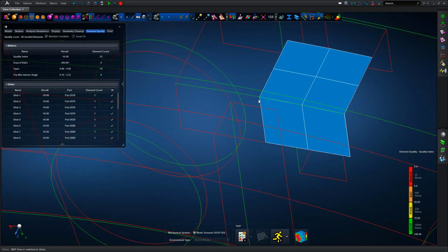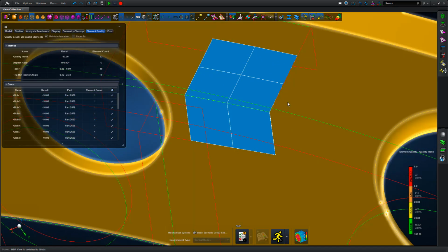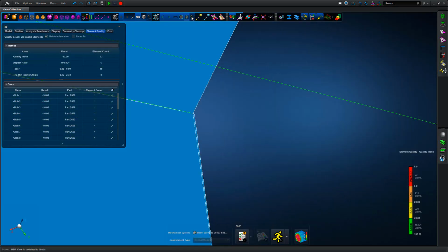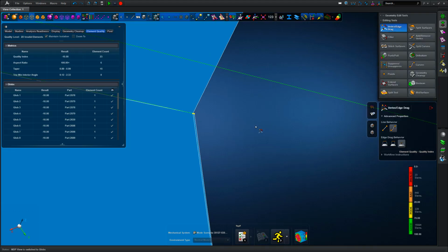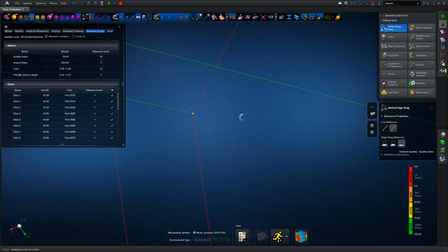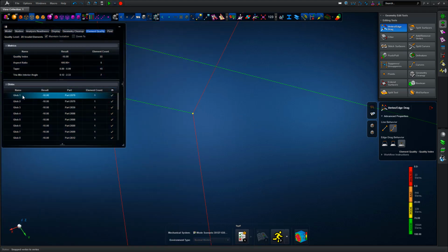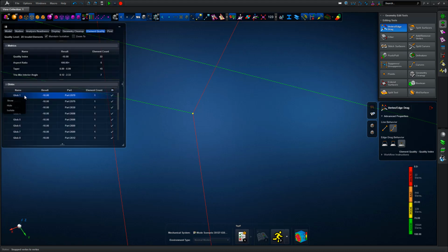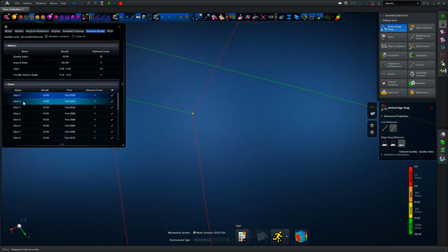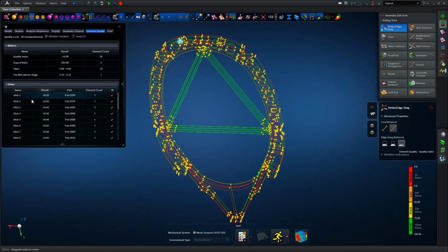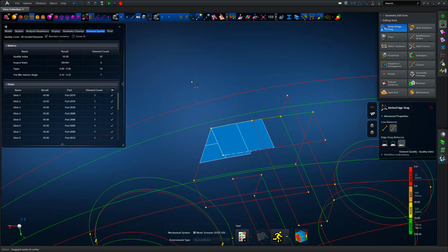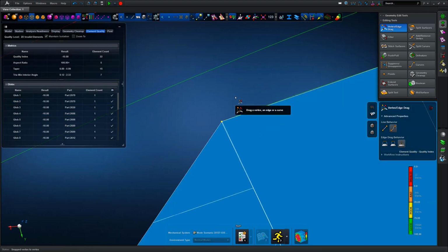We can work our way around each failed region within the model browser tree, which shows each overextension of the mid-surface as a glob, a term used here, and we can look through each one of those globs to isolate each particular region where we've got poor element quality. So, just cycling through the model.